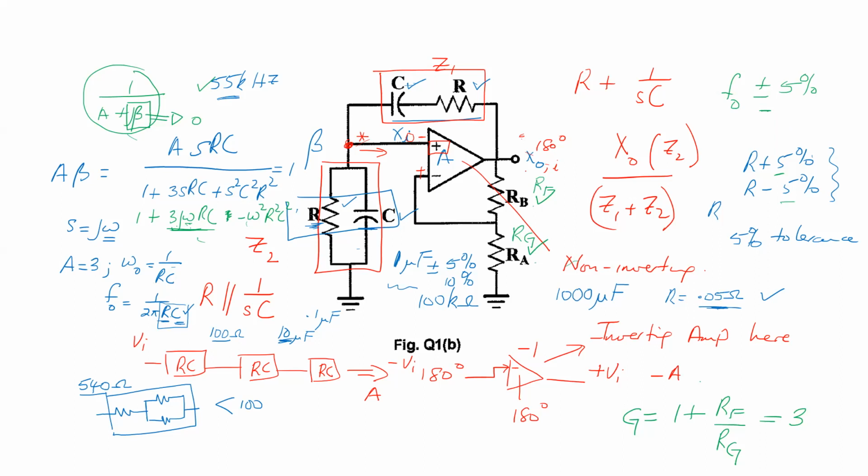And remember that too later on when you all start to do a final year project, that when you design a circuit and it works on paper, when you make it in reality and you put real components, the value of the thing is going to be a little bit different. And you explain that it's different because of the component values and so on. And then you use the actual frequency for whatever calculations you have going forward. Okay, so you don't propagate an error going forward in any design. All right? Make sense?